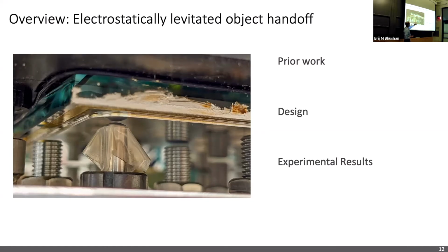The reason for that is this entire frame is connected to ground, so it is grounded. When I apply an electric field, the floater then has an electric field on it. If there is electrical contact, the floater was tending to get charged. It was picking up a charge at the time when it was breaking contact, and therefore I had to insulate it such that it's always electrically floating and it has no electrical contact. That's one I hadn't picked up on.